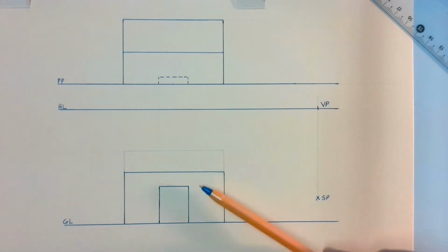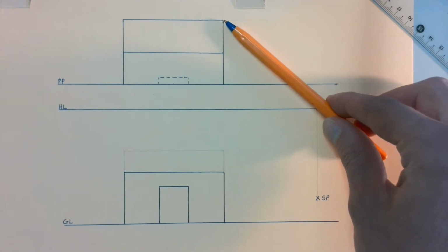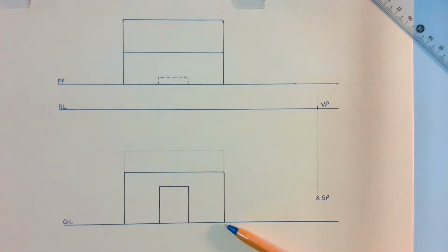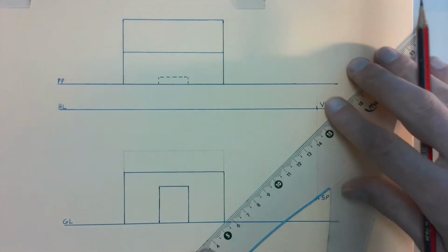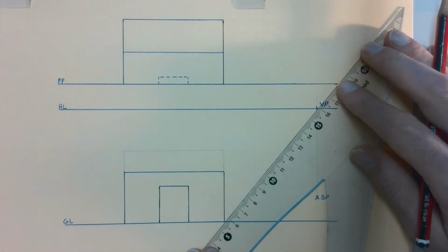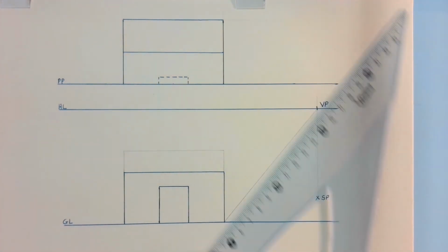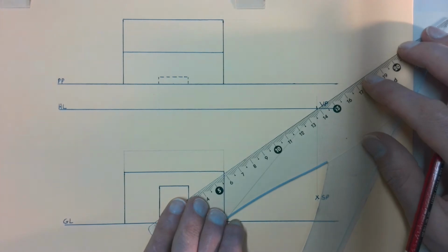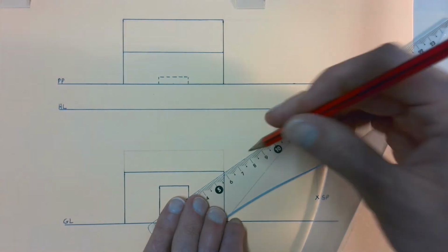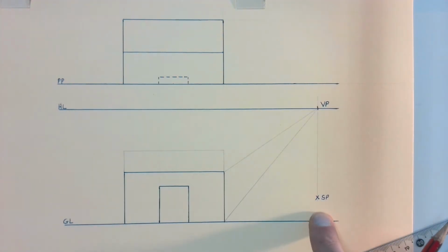Okay, so to start off with our walls, we can see that our walls start at this point and go through to that back point over there. So we're going to start off by taking the two lines on the right hand side over here through to our vanishing point with the construction line. Remember that all of our lines drawn through to our vanishing point are construction lines, nice light lines. And we're going to take the bottom of the wall as well as the top of the wall across to our vanishing point. And remember, this must go to our vanishing point, not to our standing point.